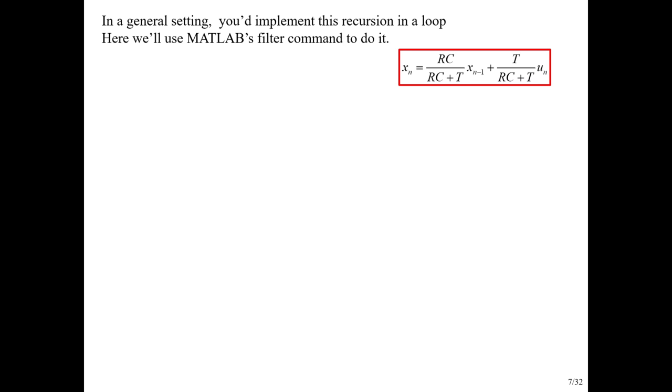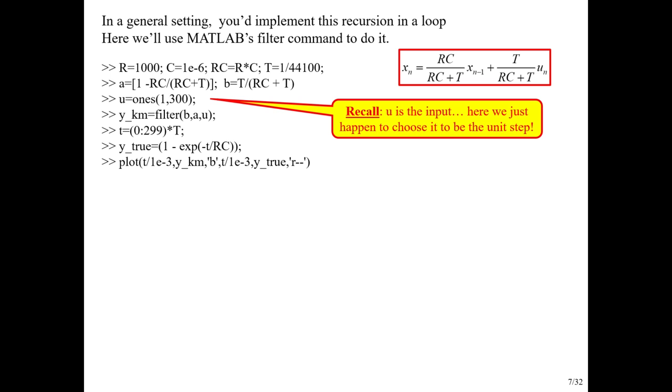But I'm going to cheat here. MATLAB's filter command basically does that recursion for me. So I'm just going to cheat and do that. Rather than computing each state value one by one as I go through a loop and converting them into outputs one by one, I'm just running the filter command, and I'm just making that assignment directly for the output equation.